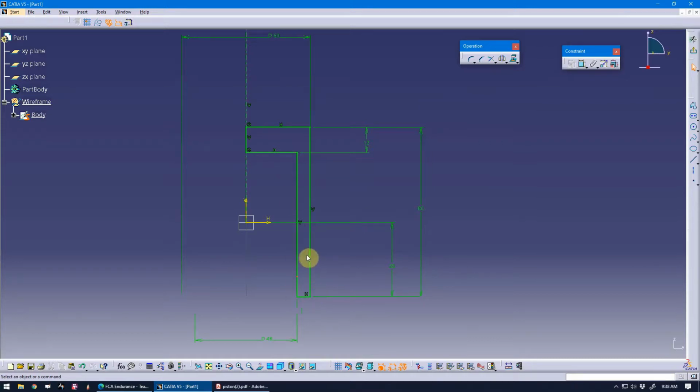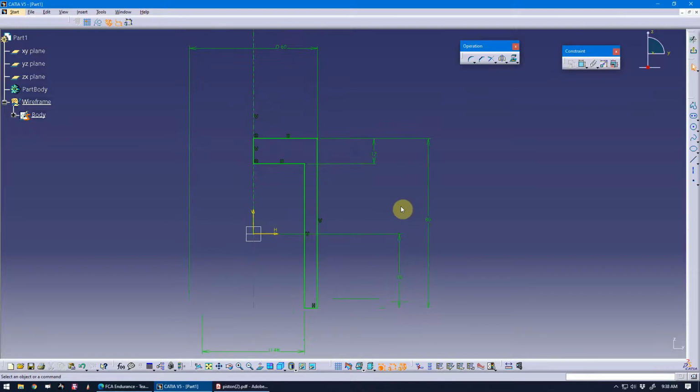I'm going to do a revolved feature. There are several dimensional constraint expectations I'm expecting from my students. One is this depth here, which is this 12 millimeters. I'm expecting that to be somewhere in the part model. And then also notice that I put my default working planes, or not my axis system, but my origin for the sketch here. And that's 35 millimeters up from the bottom.